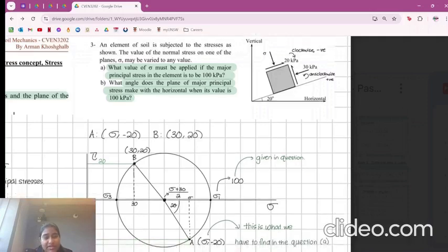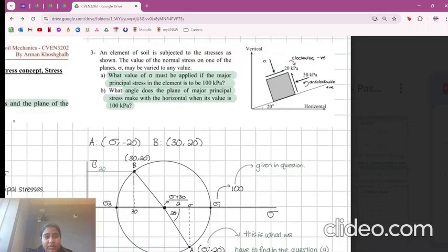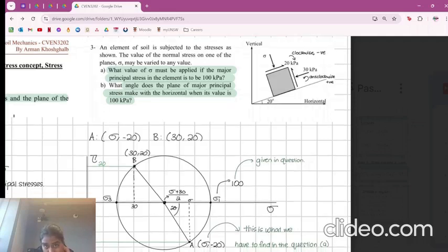So as we go through this example, I'll tell you a little bit about how to draw each section of the Mohr circle and what all of this means. The first thing that we do with any Mohr circle question is that we look at our two planes. So we've got plane A over here, and then we've got plane B here. I didn't label them in the diagram. I should have. That's a good habit to have, just because it can get really confusing with more complicated questions.